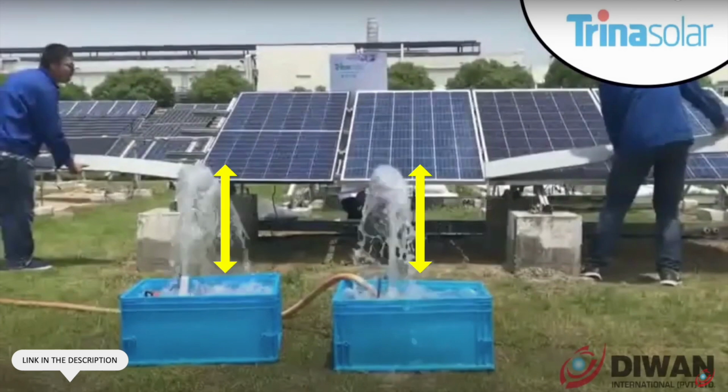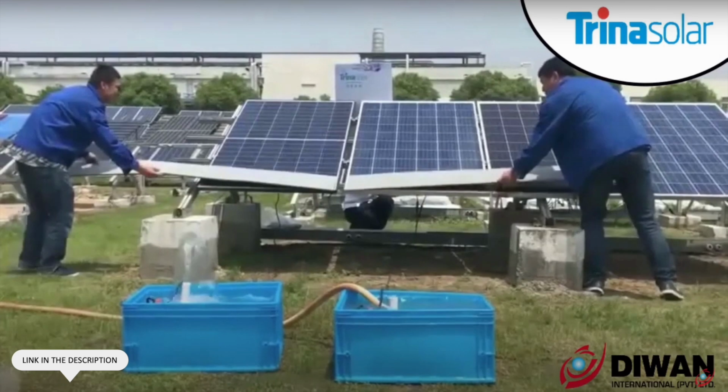The guys now shade the very bottom of both panels. Because this shading is hard shading, as you would expect, all 3 bypass diodes kick in on the full cell panel, reducing the power output to 0, and this stops the fountain. But as we can see, the fountain on the left continues operating at half power. This is just as expected because the inverter will cause the current in the panel to be lowered to avoid any of the bypass diodes kicking in.